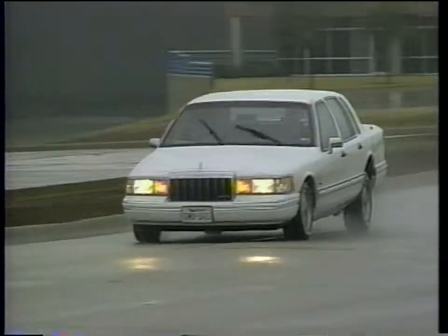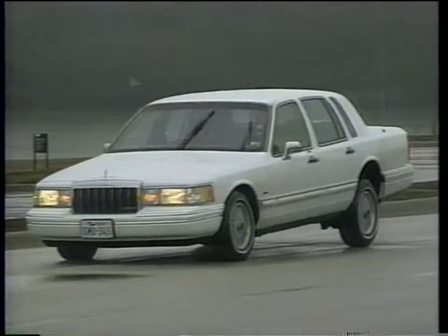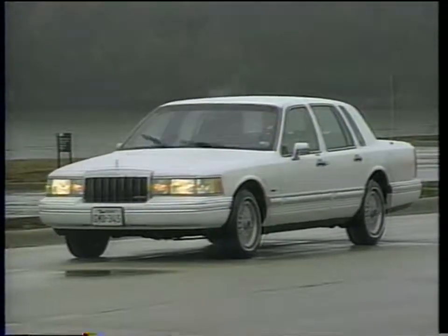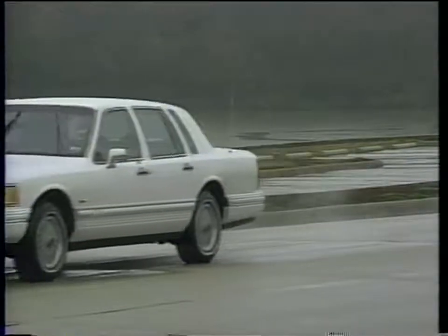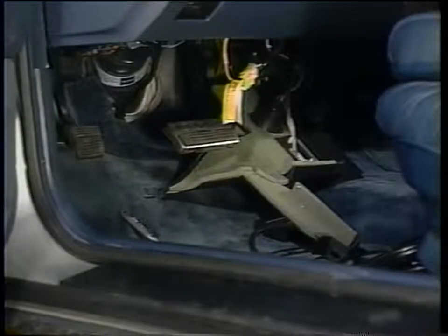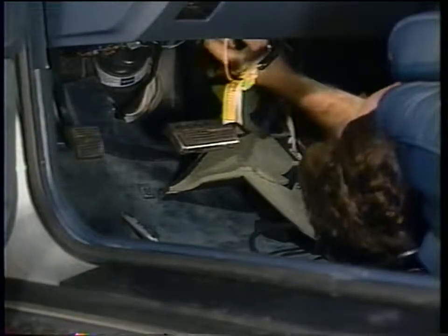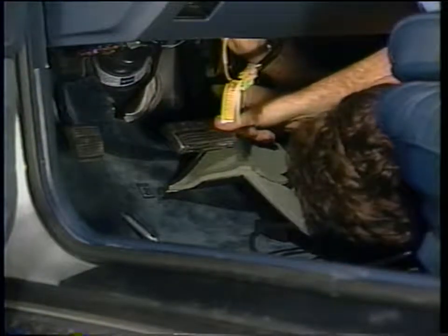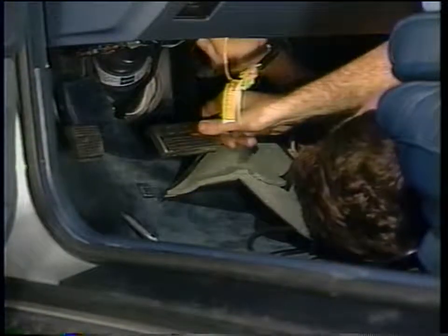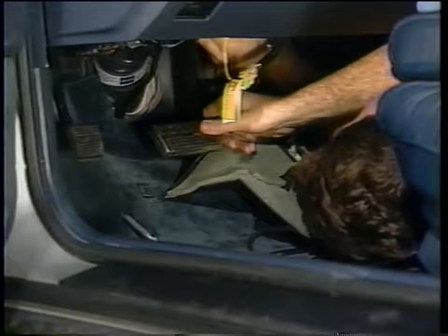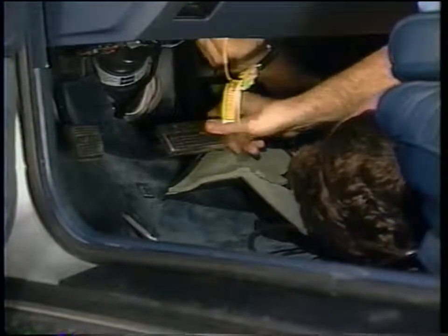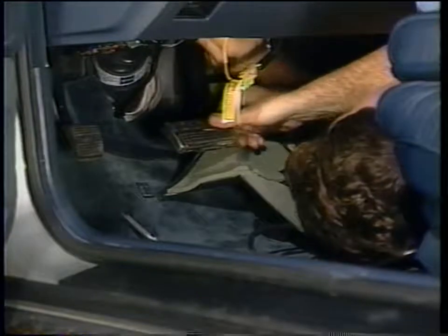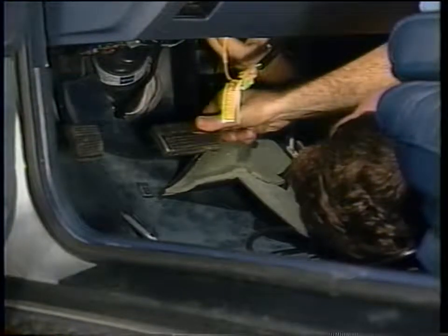The driver may hear some noise while this is occurring and feel the pedal pulsate and rise, but this is the normal way in which the system operates. It should be noted that proper adjustment and operation of the brake pedal travel switch is very important. If not correct, the driver may notice objectionable pedal feel during the entire ABS stop. The pedal will become very firm, pushing the driver's foot up to an unusually high position.